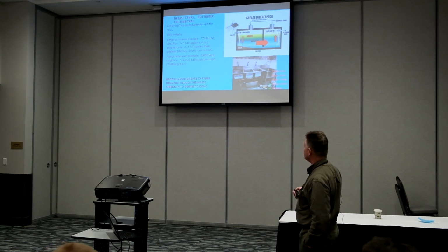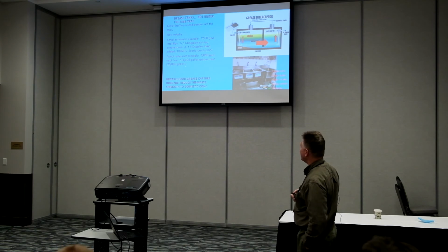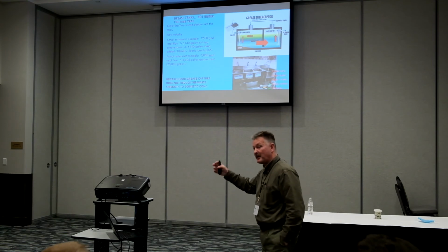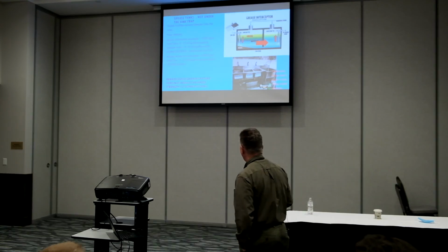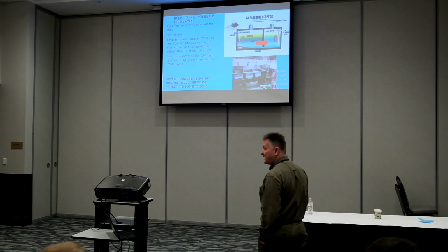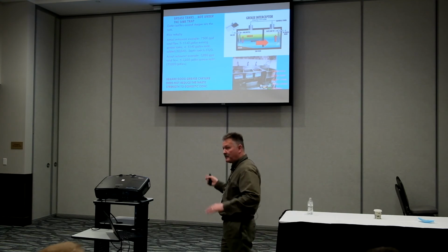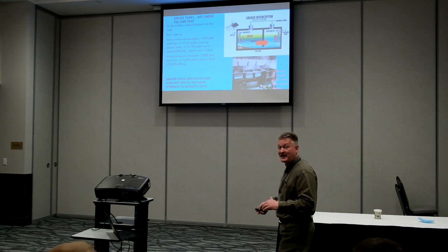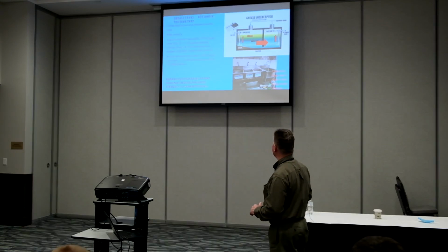Another restaurant recently involved had a 3,000 gallon a day design. It failed because of grease output into that system, part of it because of the management practices. But they went in, and now we've got 20,000 gallons of grease tankage. So far on both of these, it seems like it's working. So it's a whole lot more grease tankage than what we would normally design for.